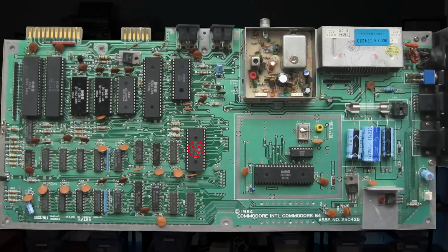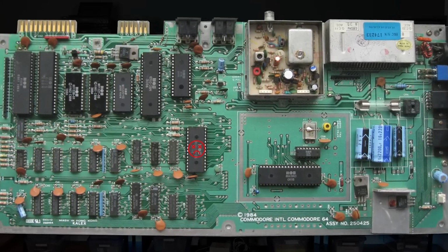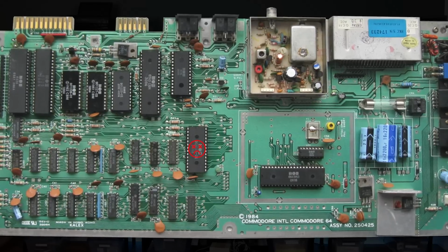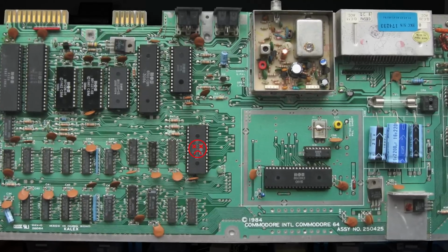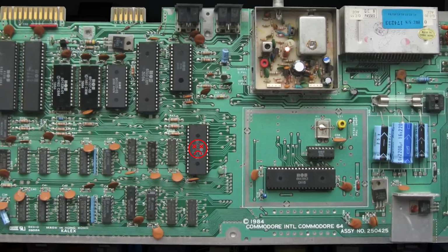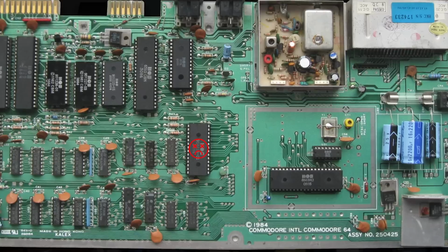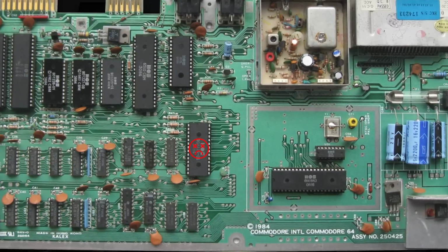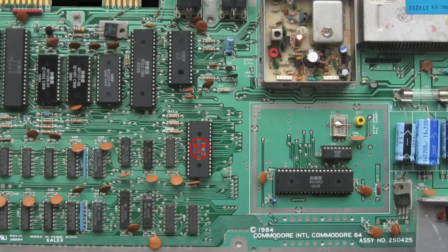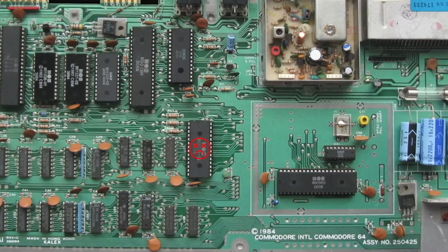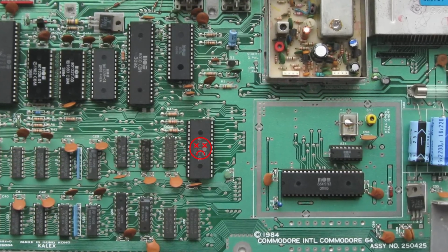One final thing before we move on. As you're probably aware, the PLA is one of the most common failure points on the C64, as these chips tend to run hot. When the PLA fails, the system may not boot at all, often displaying nothing but a blank screen. If the PLA cannot provide the correct chip select signals and timing, the memory map will not be configured correctly, meaning the CPU won't be able to access the areas of memory it needs, such as the kernel. It will therefore be unable to properly execute its startup code and the system will crash.